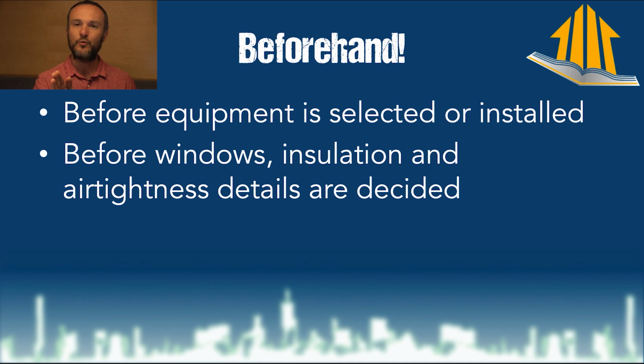So if I can go from a 24,000 BTU per hour heat loss and go down to 22,000 with some extra air sealing details that are going to cost money, I still have to install a 24,000, because that's a 2-ton. They do not make air conditioners that are 22,000. That's a bad example. You probably could find an air conditioner that would deliver 22,000 because they float around those numbers, that 2-ton, 3-ton, 2.5. But all I'm saying is, if you have to install a certain piece of equipment, making more expensive decisions on air sealing, on insulation, on windows isn't going to make any difference for you, because you still have to buy this thing. So now we're just talking about pennies of utility savings.